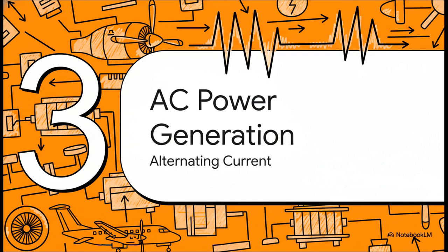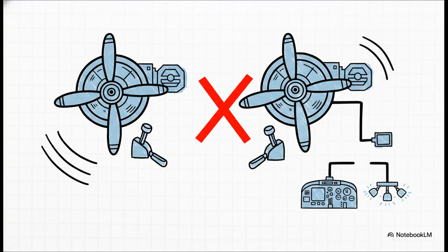Let's look at the alternating current side of the system. The Q400 is equipped with 2 115-volt AC generators mounted right on the propeller reduction gearbox. They supply variable frequency AC power anywhere between 340 and 560 Hz. But to get that power, your condition levers must be out of start and feather. They need to be in the min to max range. The major takeaway here is that while a single AC generator can handle almost all the aircraft's AC needs, except for the galley bus, which just gets shed, the system logic strictly prevents them from ever operating in parallel.